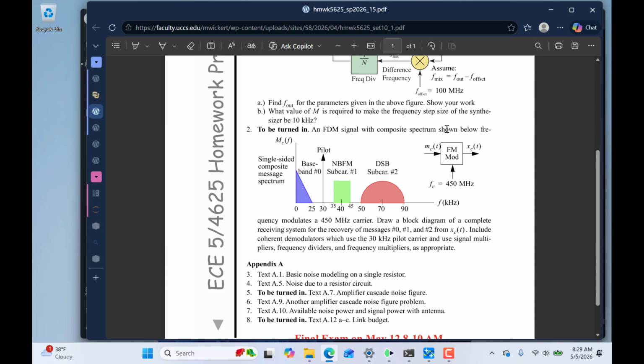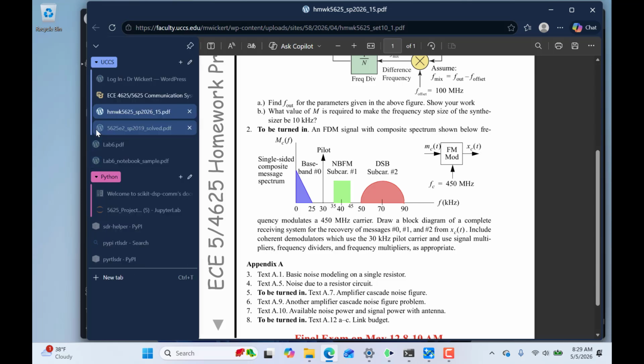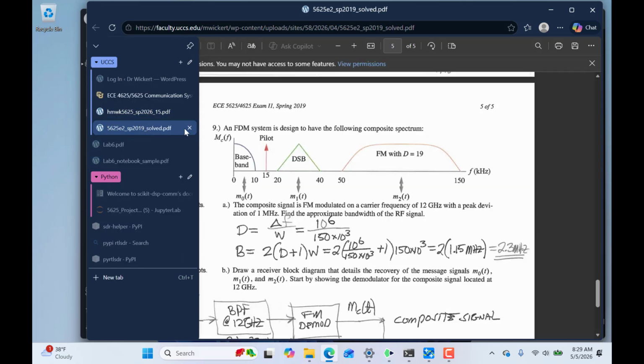The baseband is just right there. Just get it from a low pass filter. So we have a pilot at 30 kilohertz. We're going to need to have a 70 kilohertz subcarrier. So you just need to put in your block diagram how you're going to do that, and it can be a high-level block diagram that just says what you're going to do. You're going to maybe multiply 30 by something and divide it by some frequency. Remember the synthesizer ideas. You might divide it by some number and then multiply it by another number. That's another way of doing it. So I'll let you bounce that around in your head, but I'm now going to go look at an example.